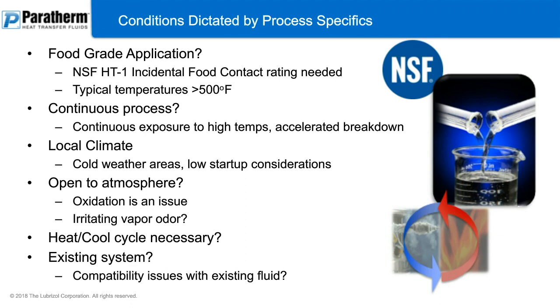Is your existing system open to atmosphere? If it is, then you're going to have oxidation issues. Also, under those circumstances, you're going to have irritating vapor odors, perhaps, depending on the fluid selection. So you're going to want to limit your choices based on those things as well. Ask the suppliers what kind of vapor odor is going to be created, because you've got people in your plant and you want to make sure they have a workable environment to be in.